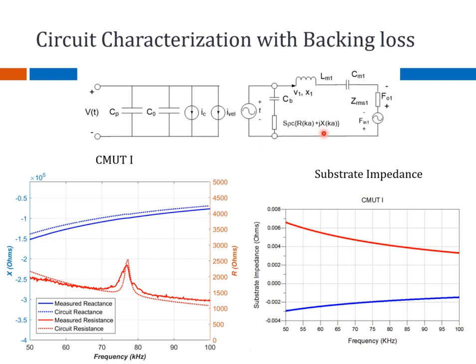And of course, people do include substrate loss, they do include frictional losses, they have dielectric losses, fine. But the substrate loss is not another source of loss, but it has to be properly modeled. That's what I'm trying to say, because it's going to affect the received performance of CMUTs as receivers, let's say.